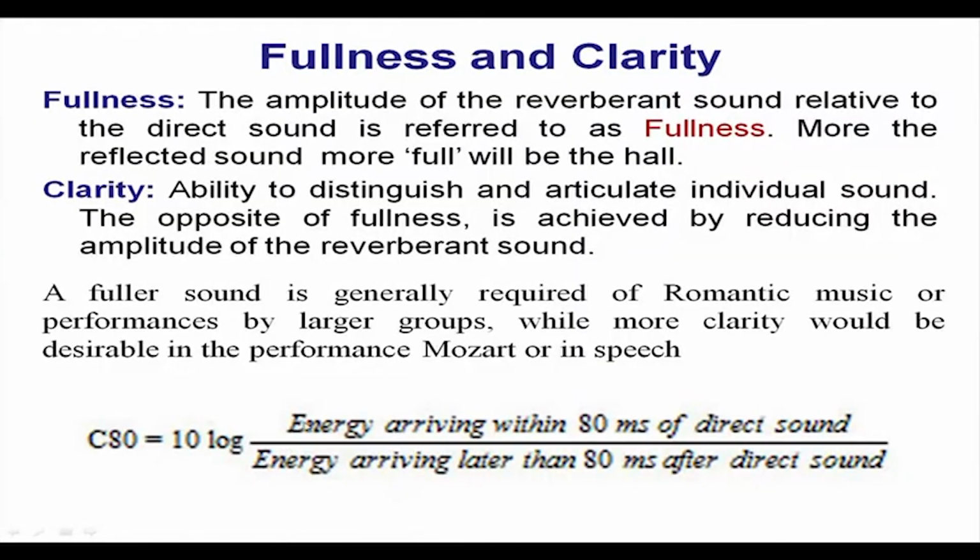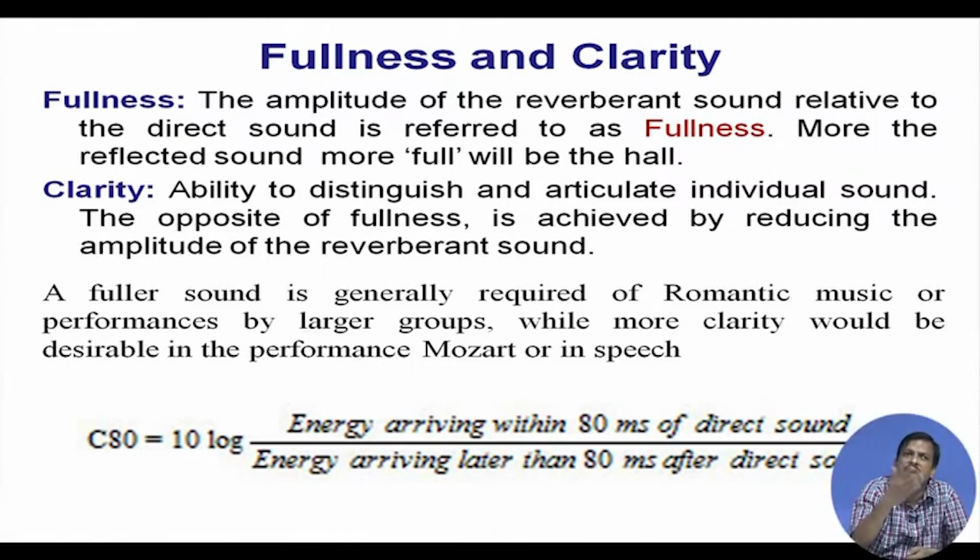Clarity C80 is defined by the energy arriving within 80 milliseconds of the direct sound relative to the energy arriving later than 80 milliseconds after the direct sound. So, within 80 milliseconds of the direct sound, some energy will come, and that energy defines the clarity.